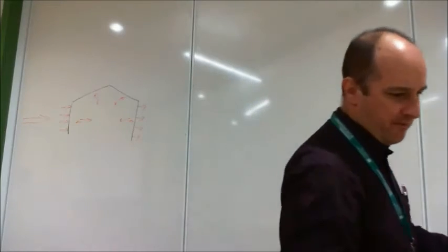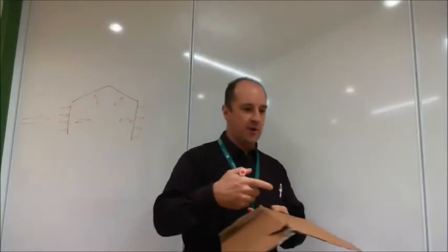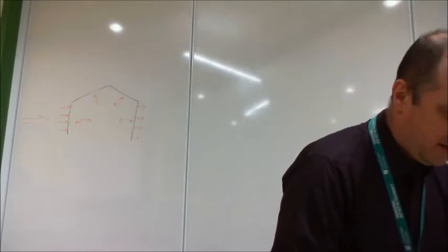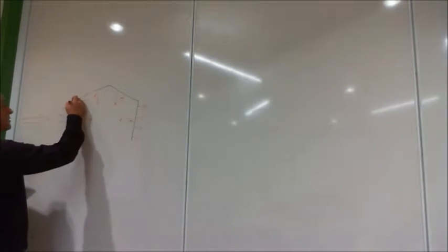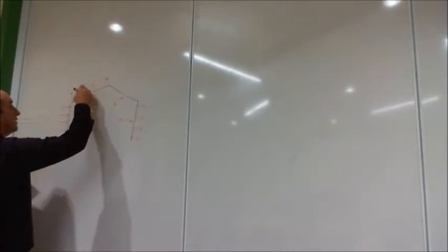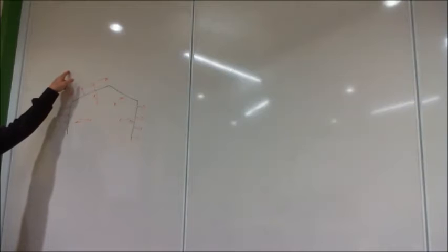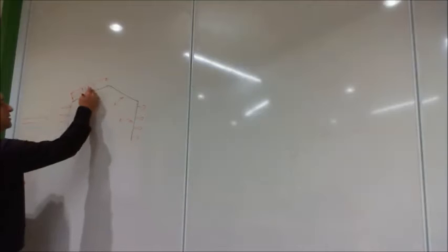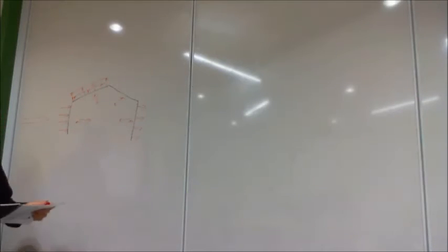Did it stop? Let's keep it still going. Good. Okay. All right. So let's imagine we've got the roof like this. The wind is blowing that way. Let's call it a, well, it doesn't really matter how steep it is, but we get two different values. You get a value like that. So that's, when I draw that, a force lifting, uplift, on the roof. And I'm going to have a second value, which I'll draw here underneath, a slightly smaller value. That's on the windward side.